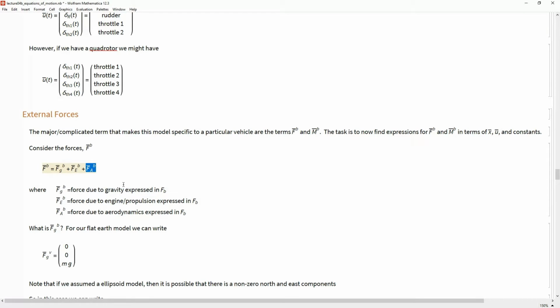And we were talking about, well, where would you be able to get the data to populate, or to model, this aerodynamic force? Well, that's exactly why we're going to go to the wind tunnel, because a wind tunnel is going to allow us to get static aerodynamic forces, which again are different than unsteady or dynamic aerodynamic forces. That's a discussion for a later day, but the strong function of this F_A is mostly steady aerodynamic forces, right? So we're going to go to the wind tunnel to try to characterize this term,